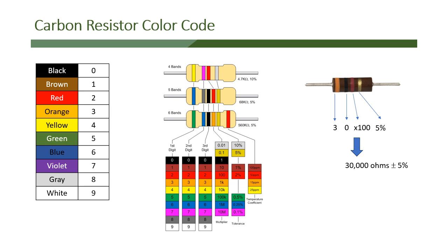And I will tell you, when they burn out, they produce a lot of smoke and they smell bad. Remember that dummy load? Well, at a 100-watt transmitter, putting out 100 watts into that dummy load means that that resistor has to be able to handle the heat of 100 watts. That dummy load is about 1.5 inches in diameter with all the fins. The resistor itself is smaller than what's in that package, but the fins allow it to dissipate the heat, so it can be a little bit smaller than it would be without the fins or heat sinks on it. So the diameter indicates the wattage. The bands indicate the value and tolerance of the resistance on a carbon composite or a carbon film resistor.